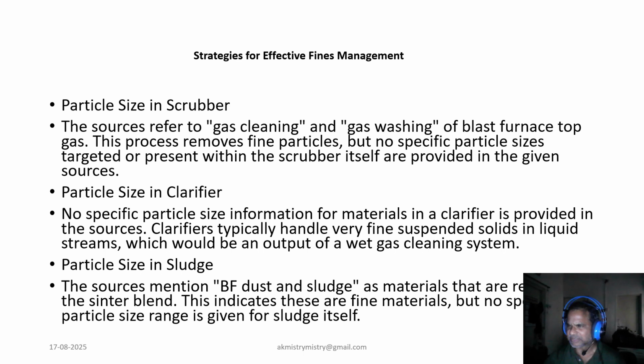Proper screening practices are also paramount, and it's standard operational practice to use a screen with a 5 mm aperture before charging burden material into the blast furnace. Rather, to be specific, that should be 6 mm. Both coke and ore burden are typically screened in the stockhouse just before charging to remove fine material.